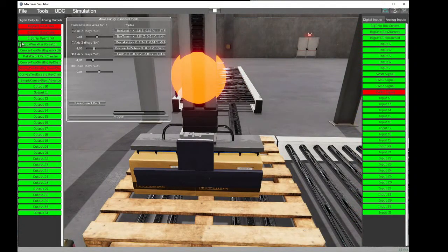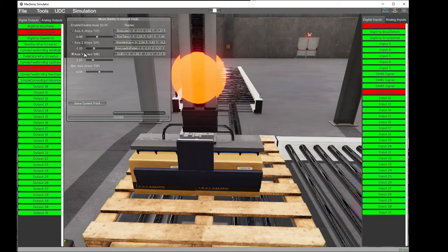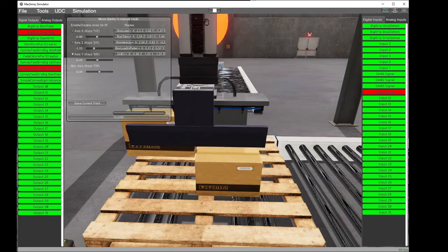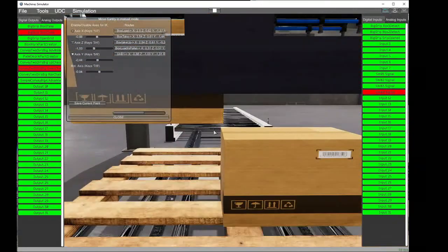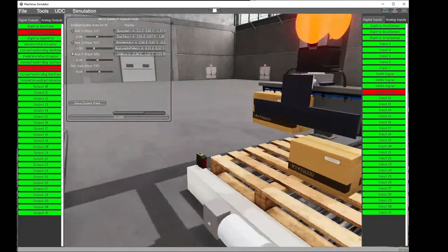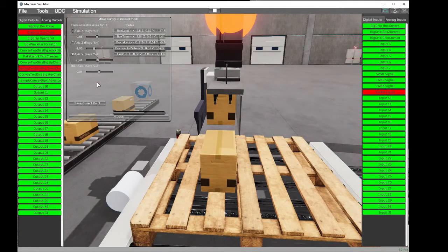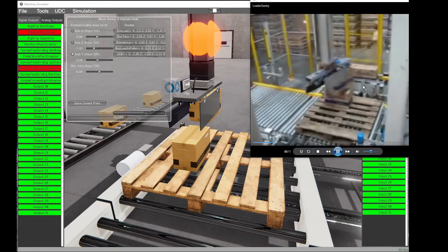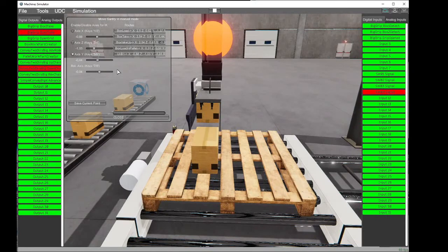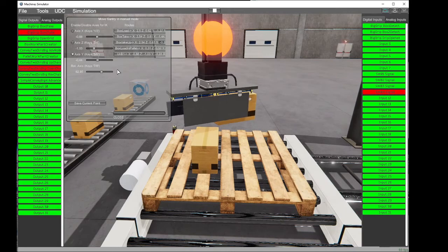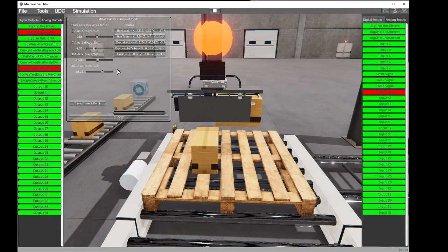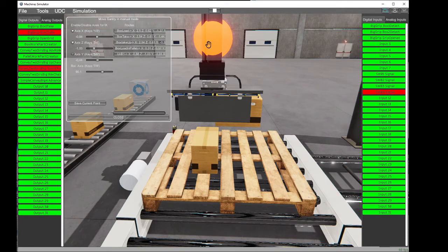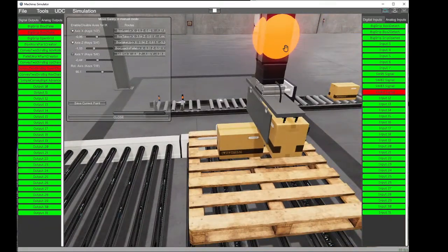Okay. Now this box we must release. Now we must raise the Y axis enough to free the box, so that when the gantry rotates it does not touch the box. Then let's rotate, in the same way as the example, to search this position. Then I rotate with keys 7, 8 until reaching 90 degrees. I press shift to reach the position with more precision. I block the Y axis. I move only X and Z.